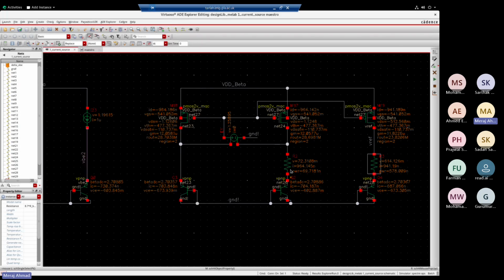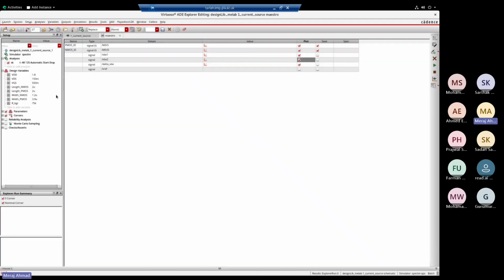So just by making this ratio, and how we set the R is something I will tell, but before that this is just the ratio. In this I have kept it 75K. Suppose initially when I design I don't know this value. So how do we set the ratio? Let me show you the waveform, how you can get its value.